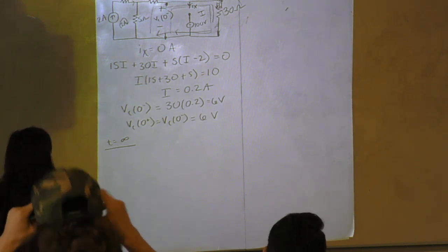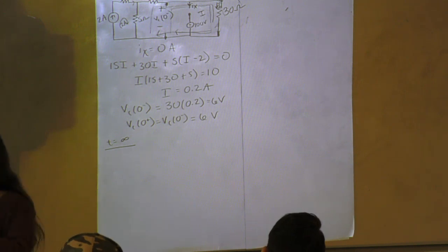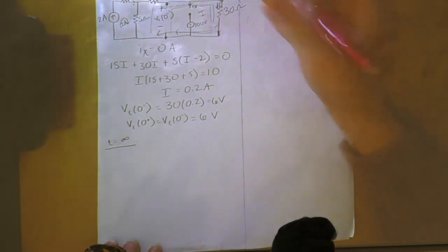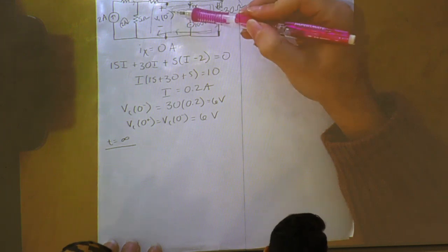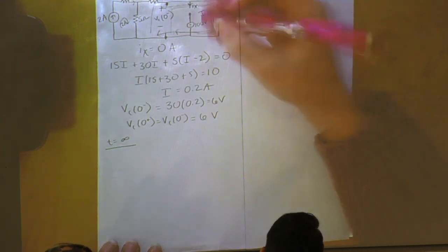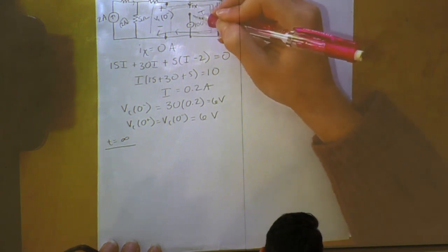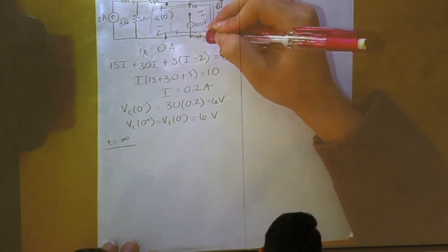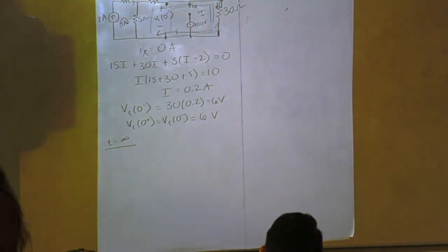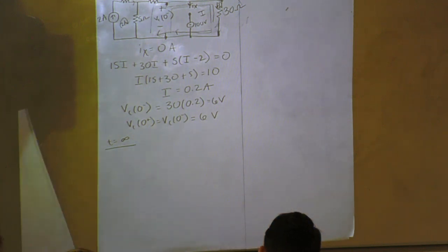Even if you're a little bit iffy on why it doesn't matter, you could try including it in your KVL. So you'd go up VC, so you'd be negative VC plus the voltage over the 30, and you'd use this node, so you go up 100, so negative 100, and then you'd have to come down. It's the only way, so it cancels out, essentially. Doesn't matter though when we start doing the infinity because we've closed the switch though, right? Yeah, at the infinity, we'll have to use it. Okay. So let's go ahead and draw our infinity circuit.